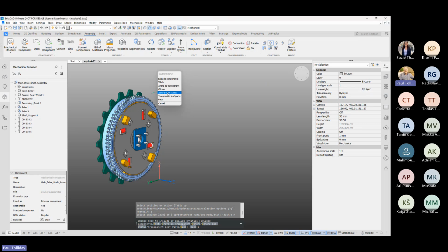If you've got an assembly here, you may have a component here that is only needed in the model. You don't want it to be shown on the bill of materials, and you can set the BOM status to be invisible in the main assembly. You may want that to be shown though on the exploded view. So what we can do is tell it to ignore that BOM status, so it actually shows the component that would normally be switched off because you're not showing that in the bill of materials. So that's one interesting one there. So we can go back here.